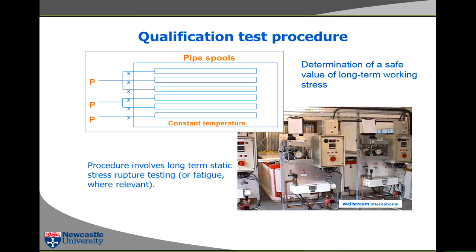This is Wellstream again. Most companies that make pipes have to do ongoing qualification tests. If you visit a thermoplastic pipe manufacturer, usually there'll be some sort of test room, and quite often they have the pipe spools tested at a constant temperature. They put the pipe spools in a water bath at constant temperature, and that will be the maximum temperature that they will run at. And they will pressurize them at constant pressure.